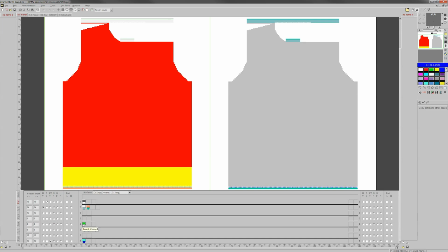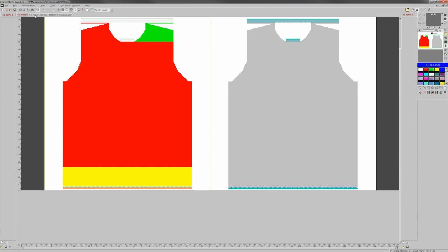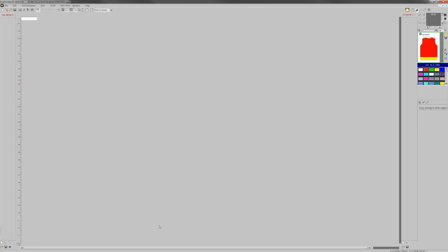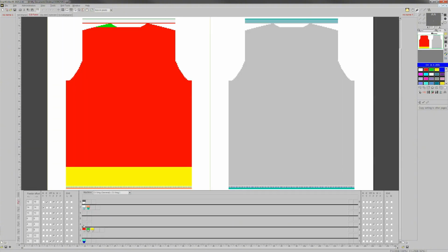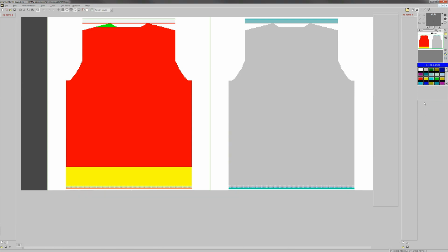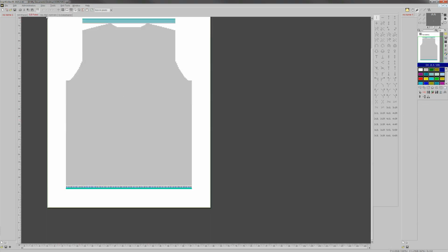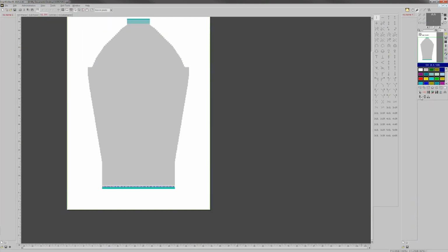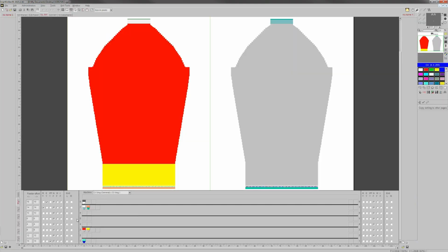Feeder 4 is used for partial knitting in the front panel. However, since the back panel doesn't require partial knitting, it is recommended to add a virtual feeder 4. This would prevent unintended release of feeder when we knit different panels continuously. We could copy feeder settings to other panels that share the same setup.